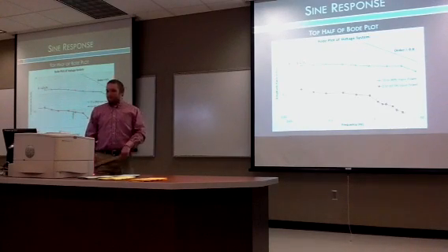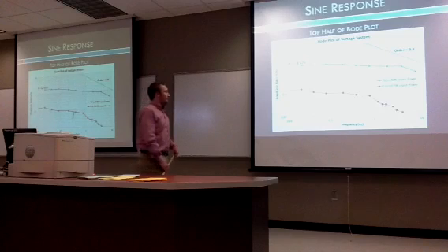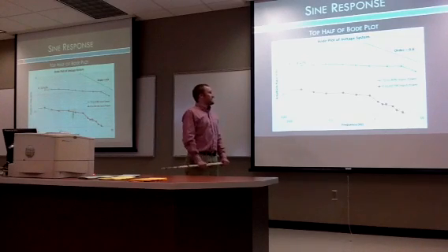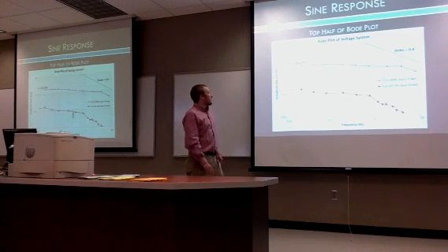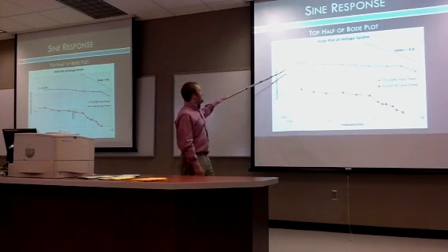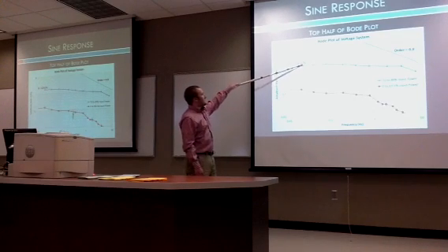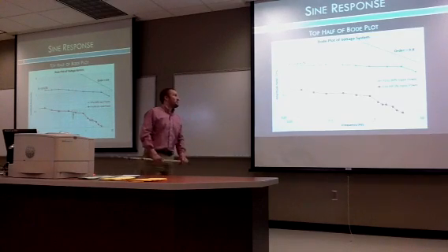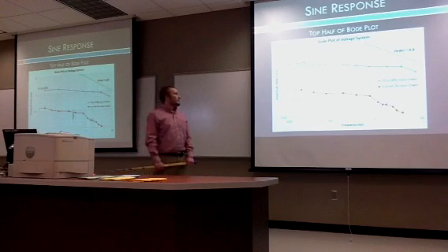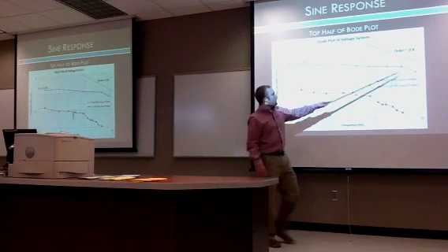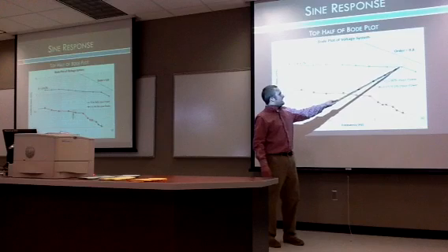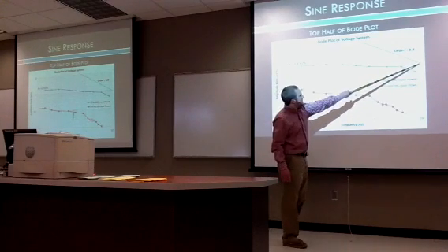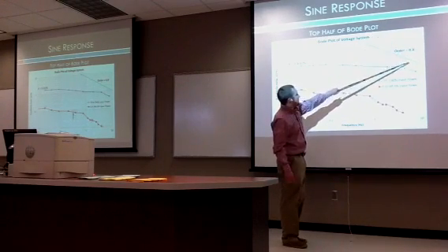Here's our Bode plot. I didn't have all the data available to me when I put this together for 69.5 to 70% input power. But for 70 to 80% input power, you can measure the gain as the frequency approaches zero, the amplitude ratio. We measured it at 1.8 volts per percent. To get the order, I drew a line parallel to the last leg, and then put it at the bottom right of one of these units on the log function.